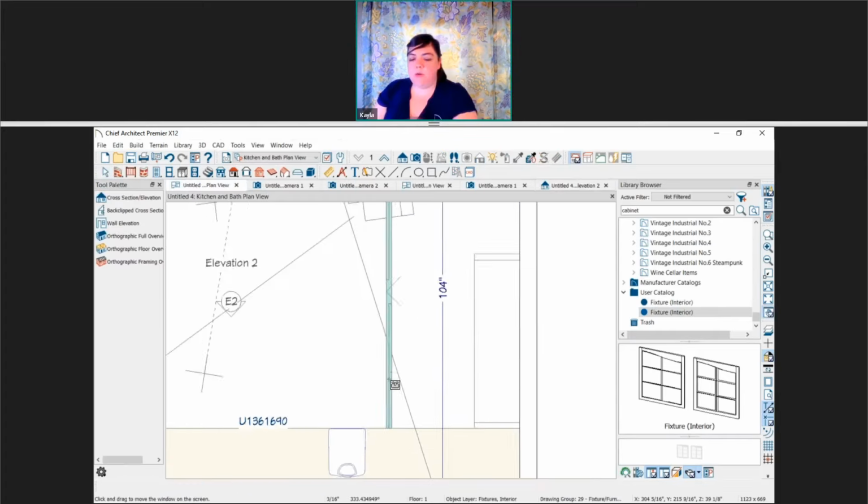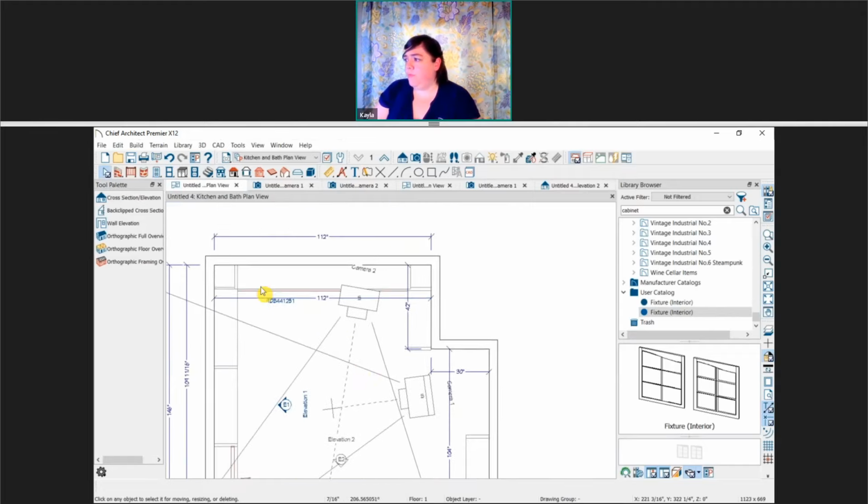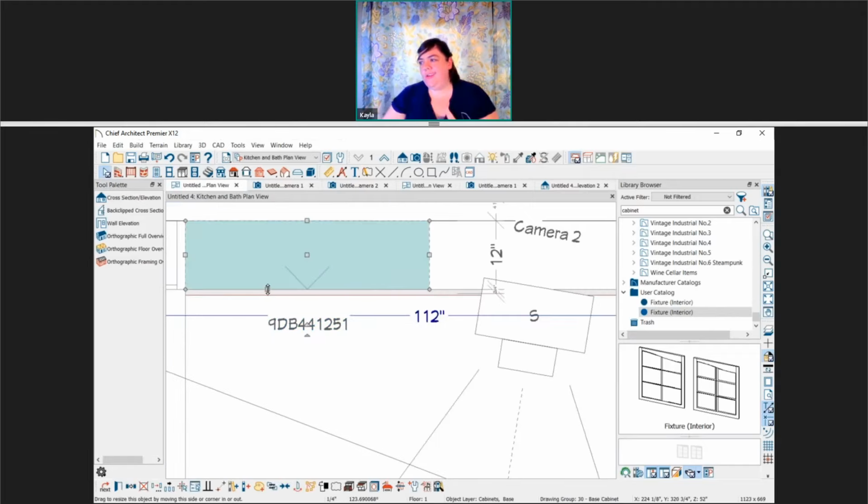So what I did was not an undo. I mentioned you can't undo within the cabinet, just within the dialog itself. So there are two ways that I get around this. One is to exit out of the dialog and save my changes every couple of steps along the way. When I make a change, I'll then select OK and open it back up. That way, if I'm doing something really complex and I make a mistake, I can just close out and undo the cabinet to the last position I saved it in.